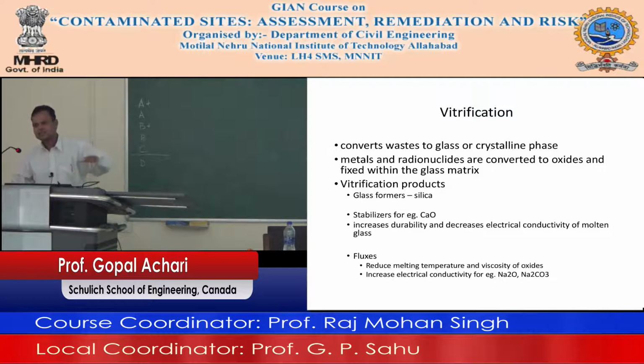Eventually the silica and alumina, the sand and the clay, which are basically silica and alumina structures, will start to melt, and once it melts, it becomes a more or less monolithic mass, and whatever is present in this environment then gets completely fixed in. Think of it like a big globule of glass. So you melt the whole thing and you fix it. That's the idea of vitrification.